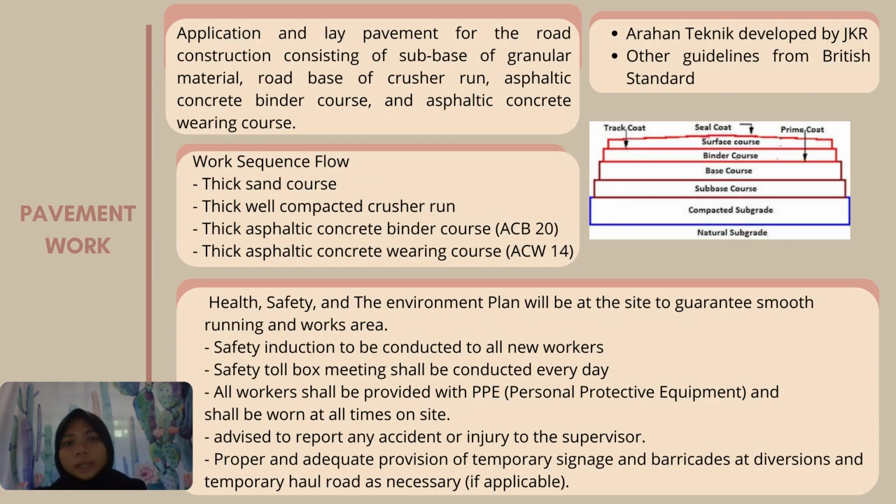The second method statement is pavement work. So for pavement work, what we have done here is the application and laying of pavement for the road, consisting of a subbase of granular material, road base of crusher run, asphaltic concrete binder course, and asphaltic concrete wearing course. The standard that we have followed: the first one is Arahan Teknik developed by JKR and other guidelines from British Standard. The work sequence flow that we have put into making this pavement is, the first level is a thick sand course, the second one is a thick well-compacted crusher run, the third one is a thick asphaltic concrete binder course ACB20, and the fourth one is a thick asphaltic concrete wearing course ACW14.